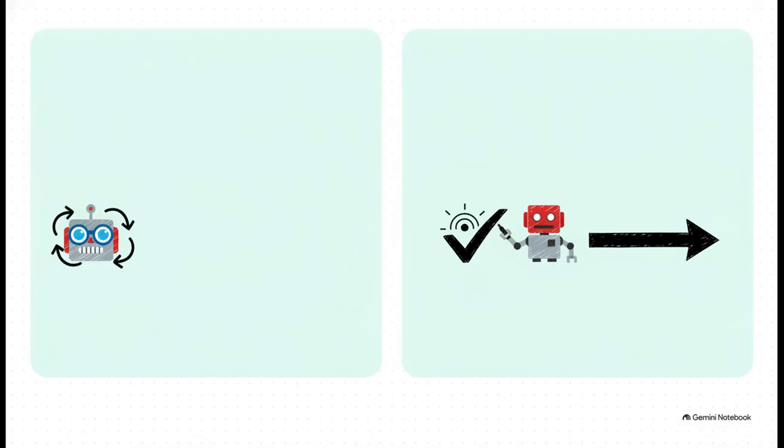All right, let's break down this exact misconception because it is a big one. The myth is that the robot always watches its sensors. This is what almost everyone assumes when they first learn about conditionals, like if statements. You write your code and think, hey, I wrote if there is an obstacle, stop. So the robot is obviously going to always watch for an obstacle. But the reality of the code is that the robot checks the sensor exactly once at startup. If you just drop a standard if statement into your program sequence, the code reads it one single time, makes a decision in a tiny fraction of a second, and then completely moves on. It never looks back at that sensor again.